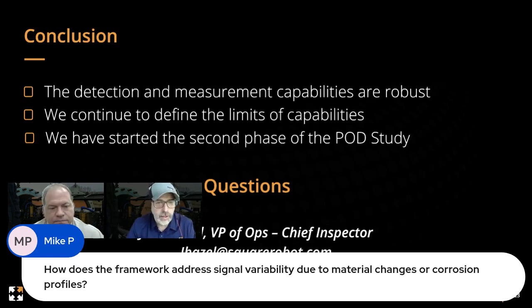The corrosion profiles, we're able to see really well soil side and product side corrosion. We're able to determine the walking of it. A lot of the product side corrosion depths we can measure, but with the reflection and refraction, we do sometimes lose our signal. So what we'll do is give you the best quality signal that we can see and let you know that. John, if you want to fill in any blanks I left.